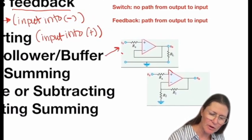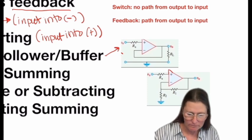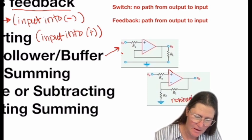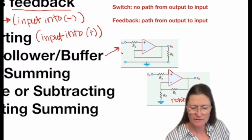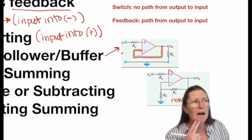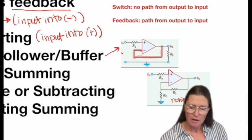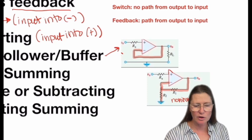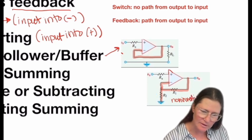This is the voltage follower or buffer, and the one below it is which one? Correct, non-inverting. And so the difference is that this pathway goes directly from the output right back to the input, and there's also no pathway to ground from there. Here, there is a pathway back, but then there's also a pathway to ground. That's the difference.